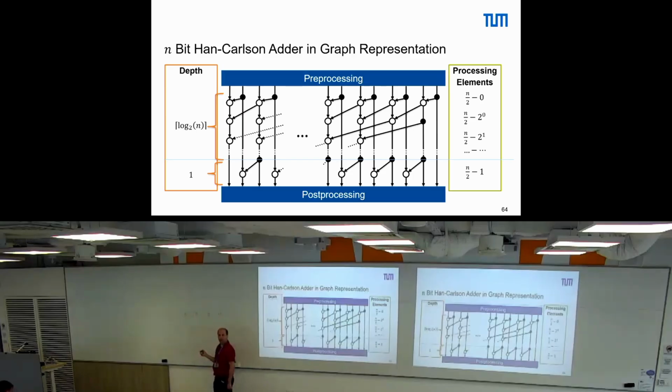Where did it go into? Yeah. So we have here a full adder, here a full adder, here a full adder, here a full adder. Well, this can also be a half adder. I just write the full adder here because it's simpler for me now. So we have a full adder and put the carry in to 0. That's a half adder. Carry chain, that's a ripple carry adder.